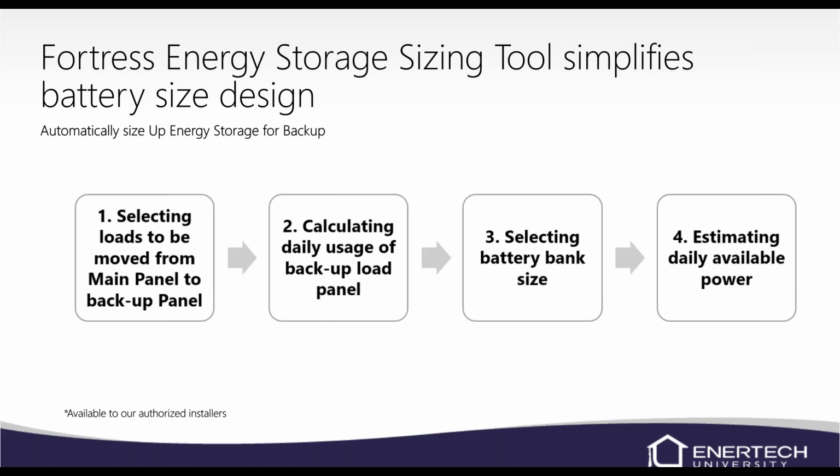So the first step you're going to do is select the loads to be moved from the main panel to your backup panel. Then you're going to calculate the daily usage of your backup load panel, which will in turn select the battery bank size and also estimate the daily power available.